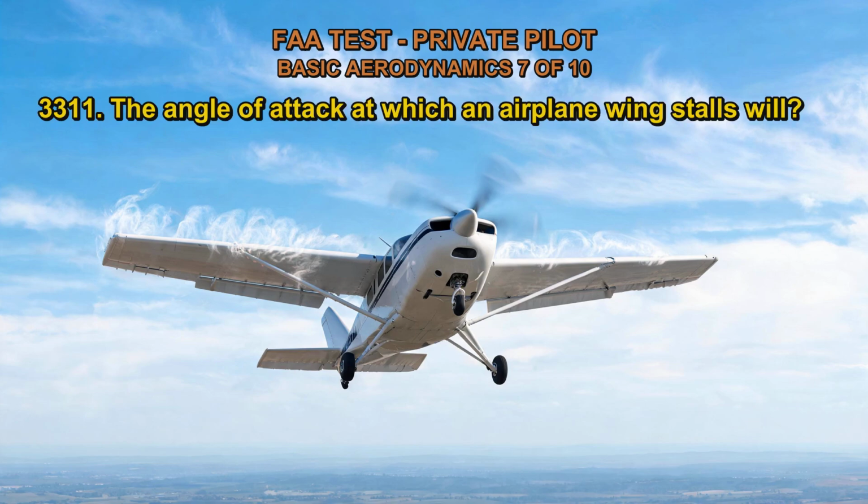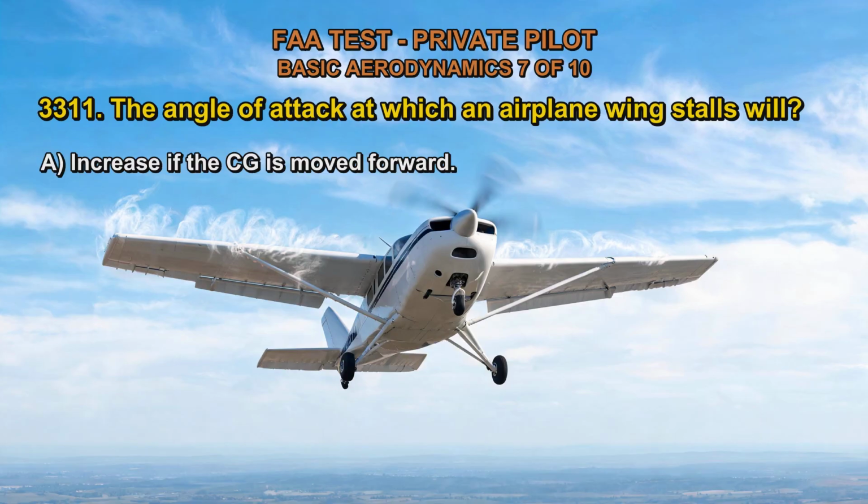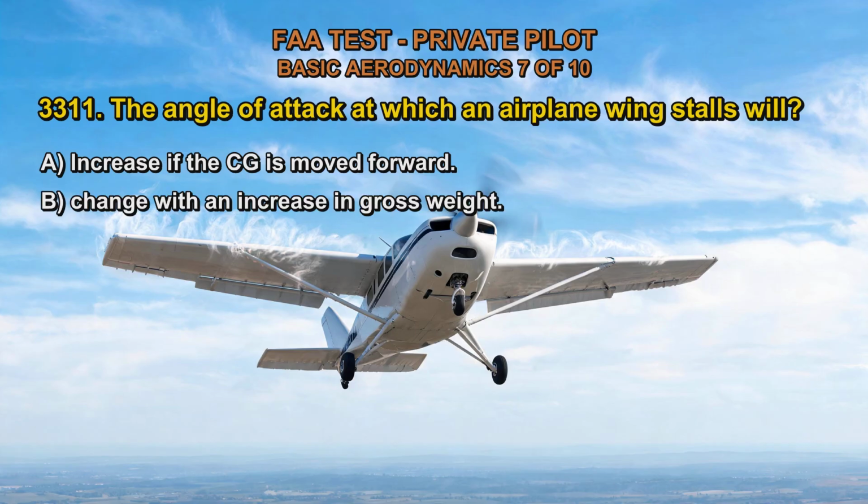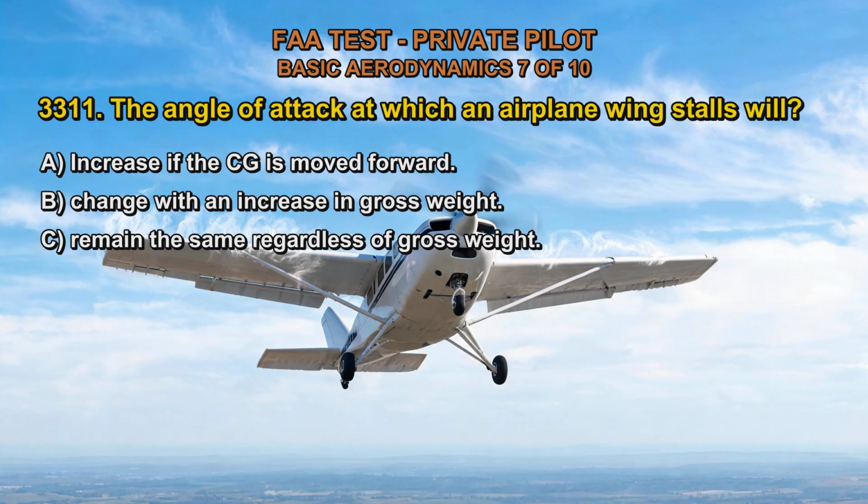Q3311. The angle of attack at which an airplane wing stalls will: A. Increase if the CG is moved forward. B. Change with an increase in gross weight. C. Remain the same regardless of gross weight. The correct answer is C.